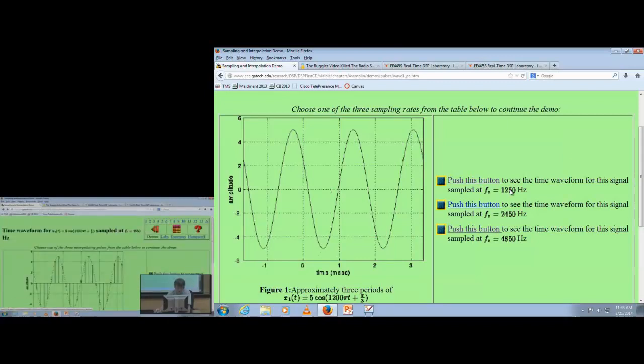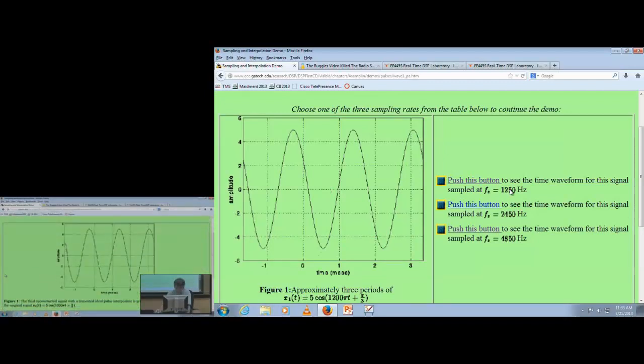And lastly, the truncated sinc at 4x oversampling, pretty amazing. A little bit of miss in the beginning, and that's due to the group delay of the filter. Very good. After that, man, it's right on. It's just tracking. Okay, so here again, this oversampling is a good thing for signal quality.